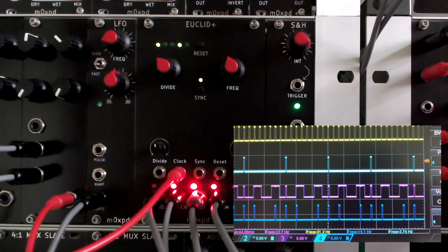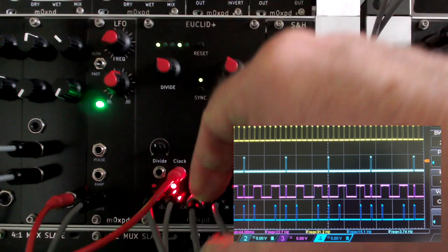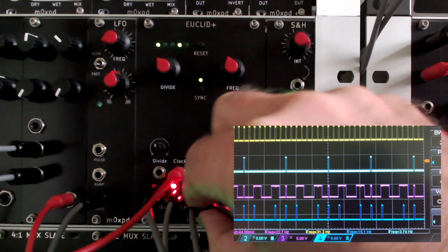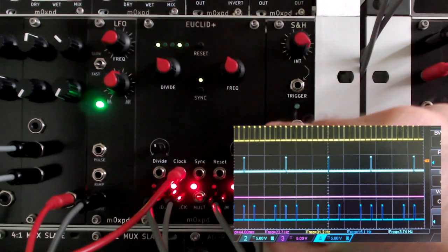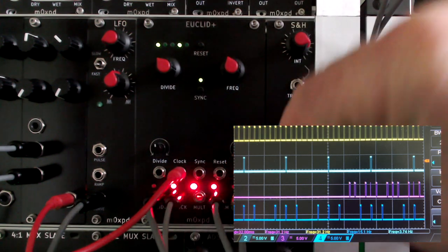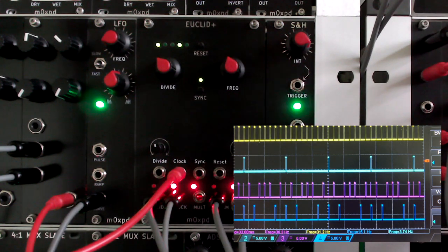And if I swap the oscilloscope channel that was looking at the oscillator output for what is called the comp, short for complement output, you'll see that the complement output is asserted on those clock pulses where the rhythm output is not asserted, so it in that sense is the complement of the rhythm output. So whenever the rhythm output is not triggered, the complement output is. You have a fixed pattern therefore generated on every cycle of this 8 pulse repeating pattern.